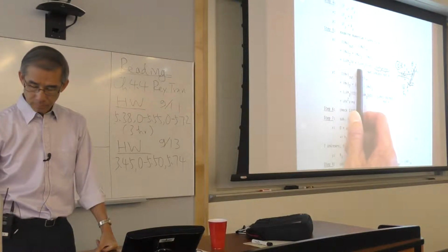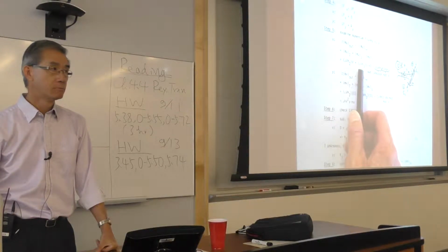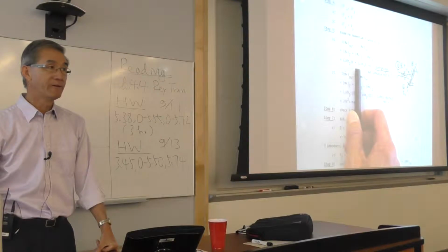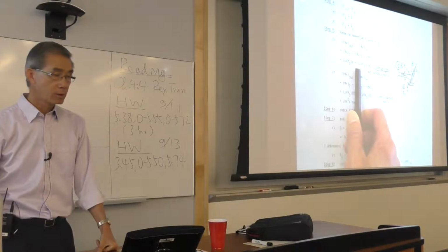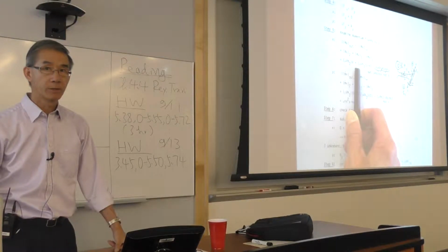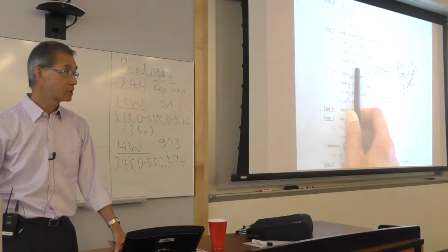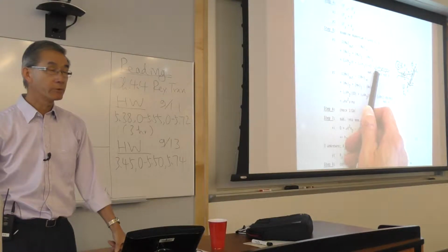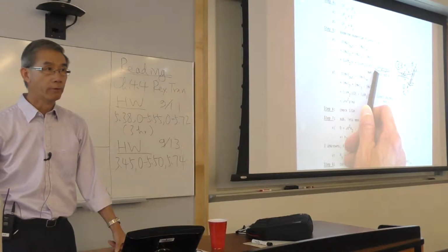Second term, change it to h3. By the way, the problem statement stated the velocity is everywhere equal to V, and that you learned in another 2 lectures is because of Bernoulli. But right now it's given. Then the last term, doing only the m dot first, is rho V h1.